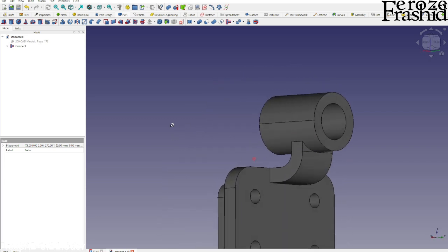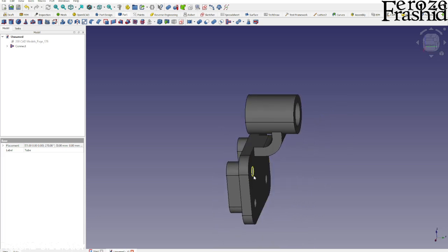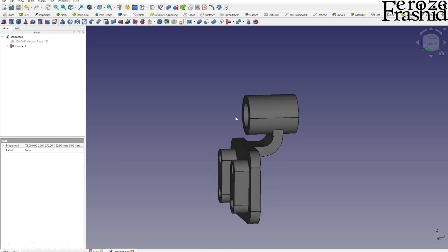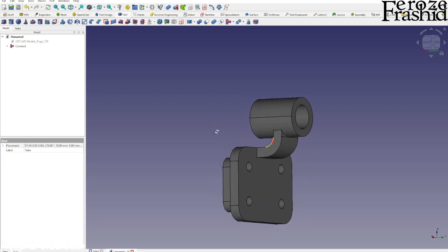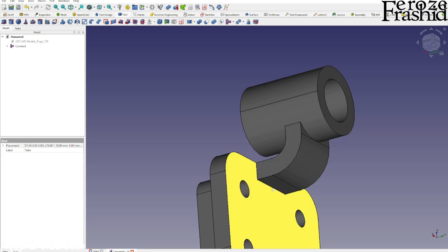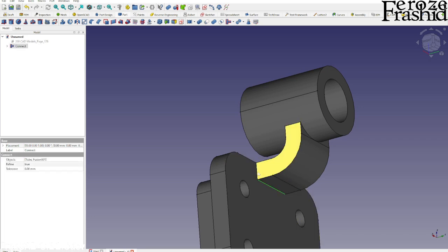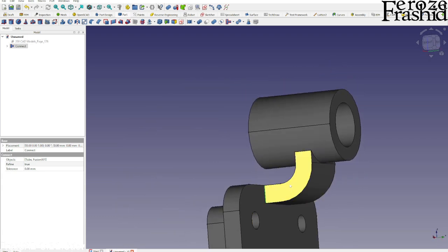So it looks like a tube holder. You screw these 4 holes into a wall or something, and then a pipe goes through here and applies some load on it. And if that's the loading pattern, I'm sure having a fillet here and here will contribute to the load resistance.